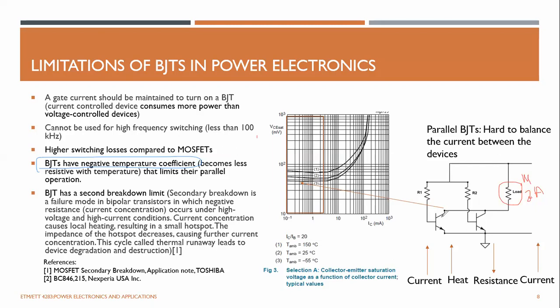Each transistor can provide a maximum of 1 amp. So you just plan to connect them in parallel. It will do the job, because when this transistor and this transistor are turned on, they are connected in parallel. So the load current will go through this transistor as well as this transistor, assuming they equally return through the emitter, right?